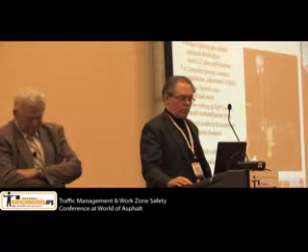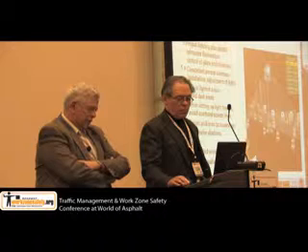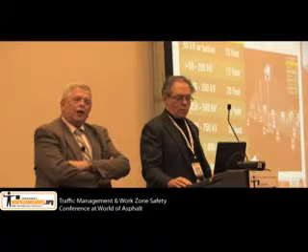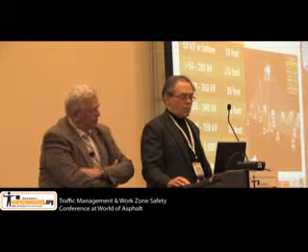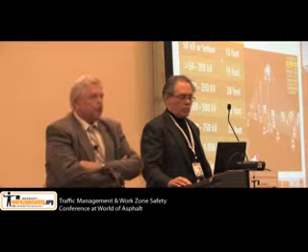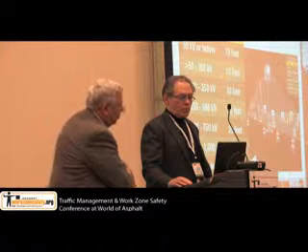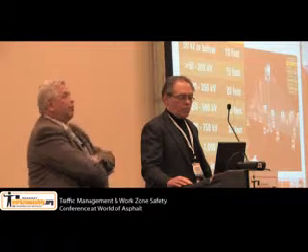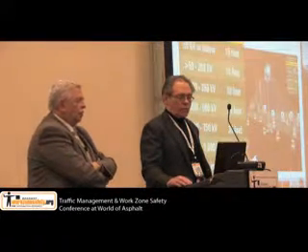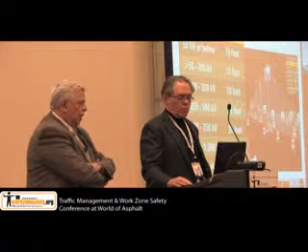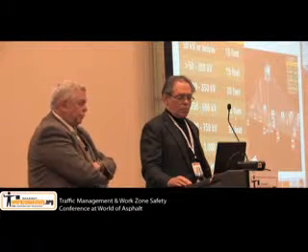And some of these are very obvious. When you're setting up light towers, try to avoid hitting overhead power lines. That will illuminate things far more than anybody wants to be illuminated. We have an interesting little chart here that says when you're dealing with light towers and so forth, safe distance from those lines. If you're looking at low, high voltage and very high voltage towers and so forth, you need to be a good distance away from them.